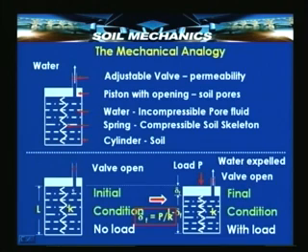As long as this valve is closed, nothing will happen. The piston will withstand the load. Since water is incompressible, the piston will remain in its original position, there will be no movement. But the moment we open this valve and allow the water to get expelled, the piston gradually moves down, and in that process the load gradually gets transferred to the spring and the spring starts compressing.